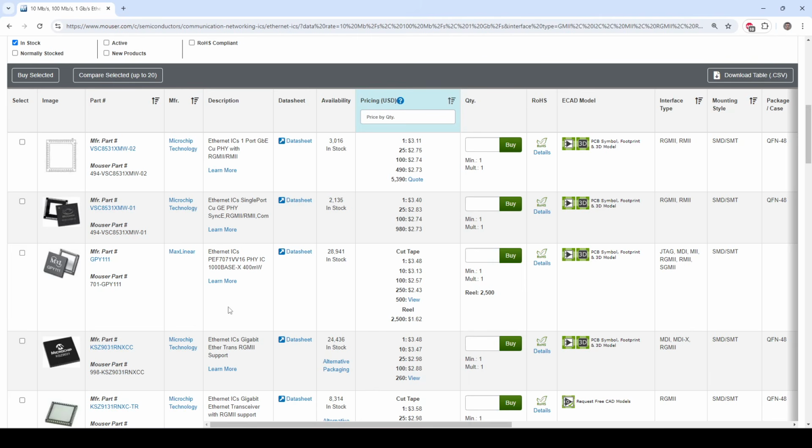In terms of compatibility, for example, for setting up the control registers of these physical layers, the basic set of control registers is actually standardized by the IEEE, so most PHYs should be compatible with whatever MAC you're using. However, there are of course exceptions, and you should definitely check that there is compatibility between your MAC and your chosen PHY or physical layer. I'd strongly suggest choosing a physical layer that's been proven to work with your MAC, and there might be already existing drivers or configuration for the PHY and MAC combination of your choice.